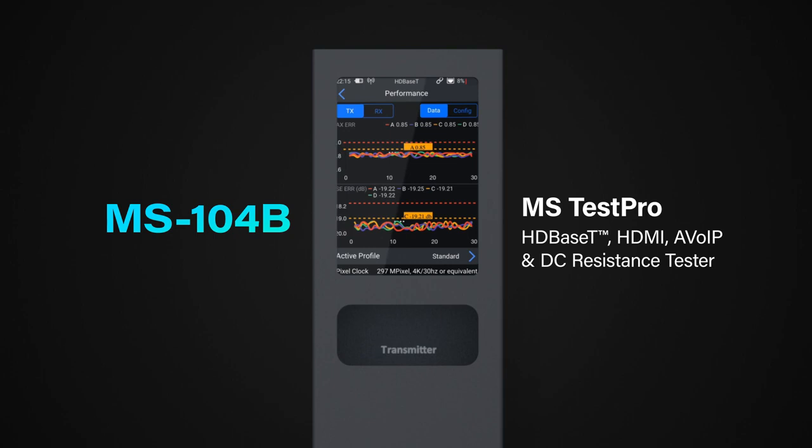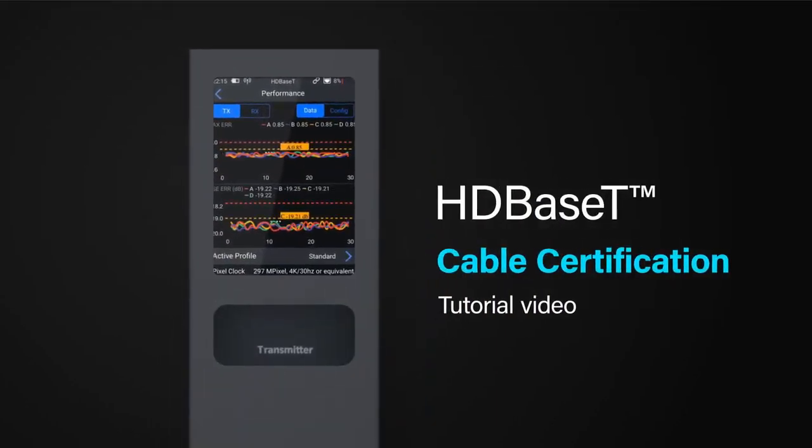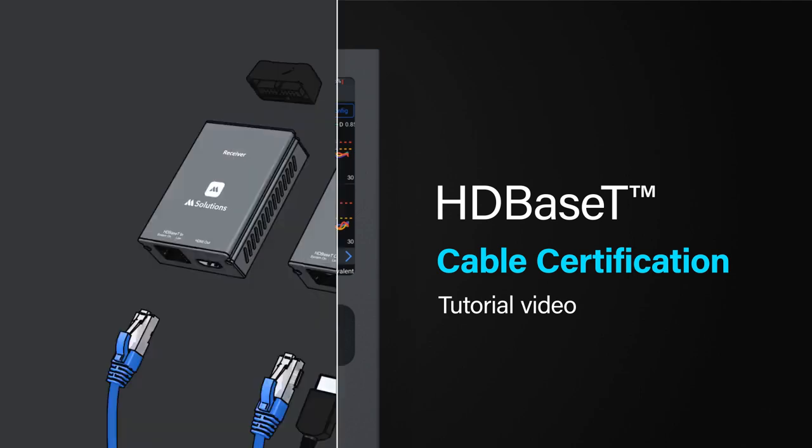The MS Test Pro is an all-in-one tool for assisting AV integrators to qualify and certify their infrastructure, both pre- and post-installation. This short video will take you through the performance and certification procedure for testing CAT cable for suitability of use with a 10 gig HDBaseT signal.